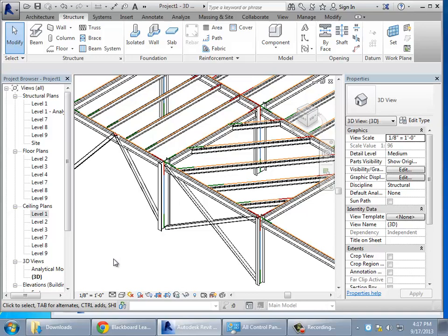Okay, so how are we feeling about this basic structural steel modeling? Is that all feeling pretty good? If you're feeling pretty good about that, excellent. We can also go ahead and put a floor slab on this. This is one of those things, again, where the architect may have put an architectural floor in there, and here you want to put a structural floor in there that actually includes the metal decking and all that. Or we can just go through and put a floor in here. It works very much the same as it does doing it architecturally.